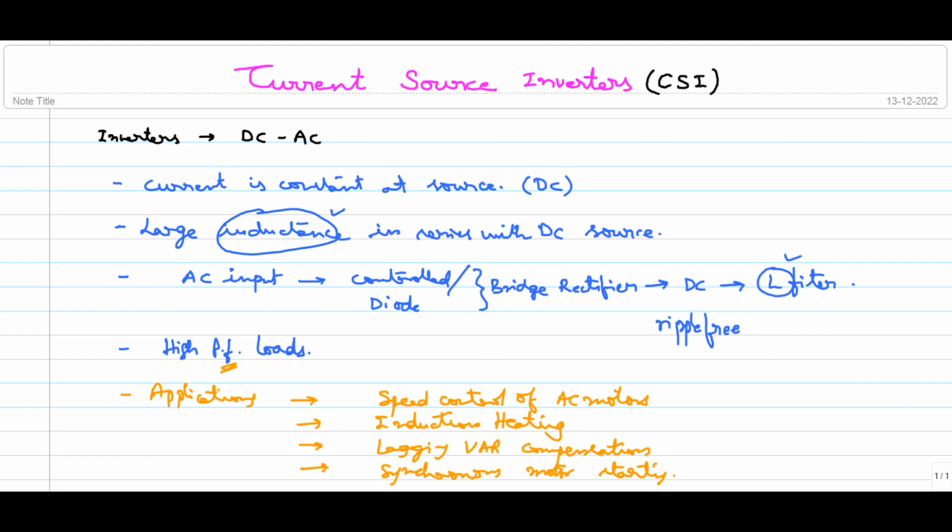So coming to which things are used with load commutation and which with forced commutation: load commutation is generally used for leading power factors and forced commutation is generally used for lagging power factors. Frankly speaking, we are dealing with more and more lagging power factors only, so we definitely require forced commutation in general applications. Of course, load commutation is also there for leading power factor.